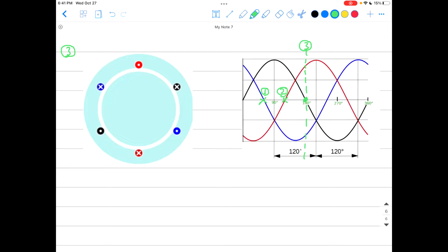And let's look at the voltages again. Okay, guys, for now the black one, VC, equals 0, so it does not have any flux. The blue one, VB, will be negative, sorry. And the red one, VA, will be positive here. I'll do the same thing. A is now positive, that means the current goes through here, into the cross and coming out of the dot. Using the right hand rule, the direction of the flux will be perpendicular to this and going this direction, from A.